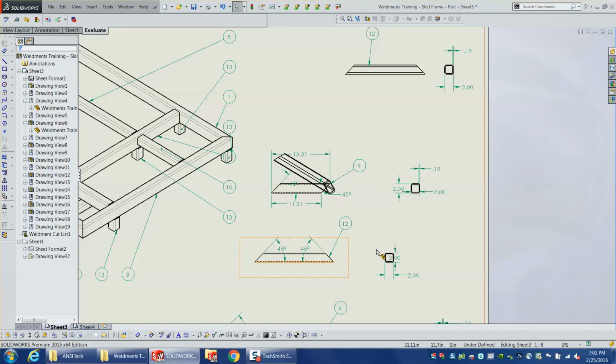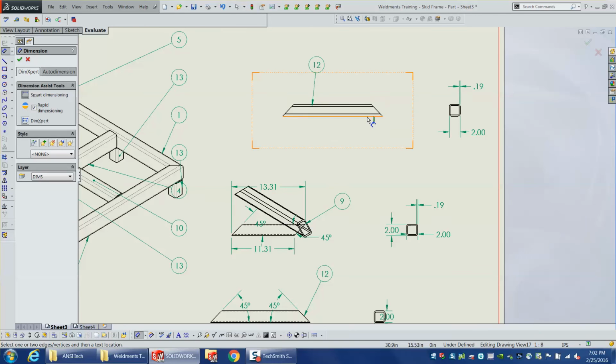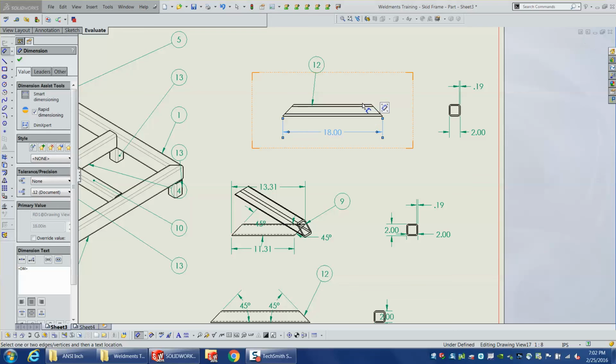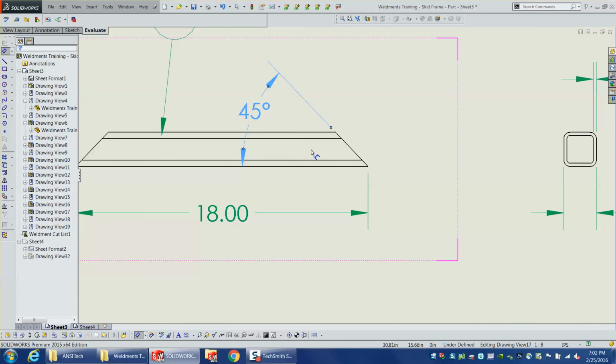So do that before you delete your view that's slightly tilted. Wouldn't that take longer than just dimensioning it from scratch? Maybe. It depends how hard it was to place that dimension, but yeah, you have options. Yeah, it's hard to put dimensions. If it's me, it might be quicker just to dimension them and use smart dimensioning to put it where it needs to go, but sometimes these angle ones are a little tricky. A lot of times you pick a tangent when you do this.